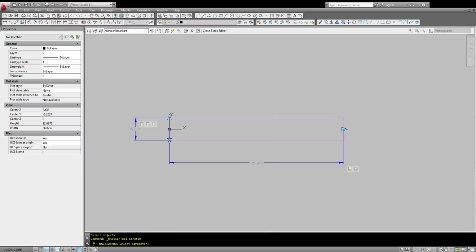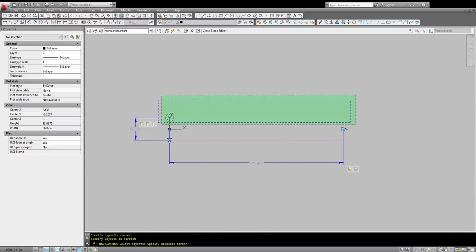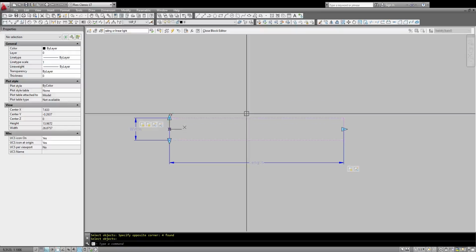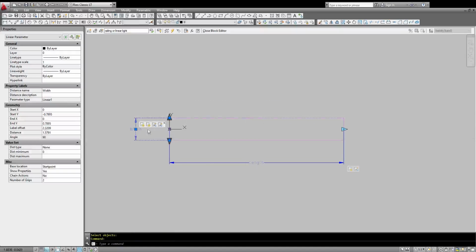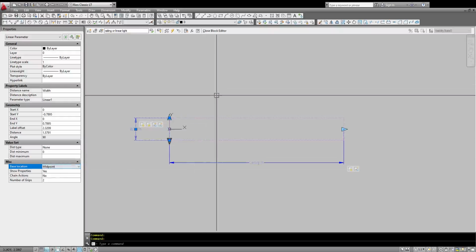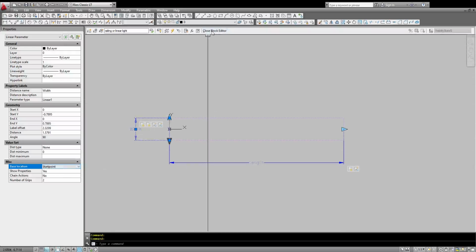Okay. Okay, tap the area where it stretches. Everything inside that area should move with that thing. Okay, that's it. And there's an option here. You can stretch it one at a time, each side, but you can stretch it at the same time, like in a chain. Base location can be midpoint, and then so it stretches. Well, I'll show you. Start point as the base location. Save.